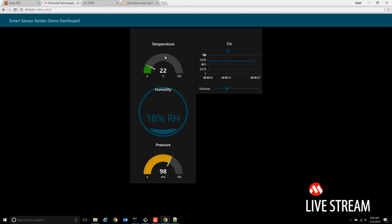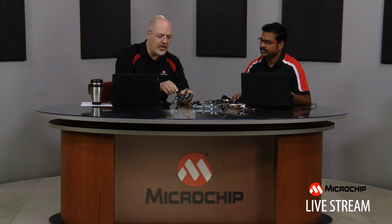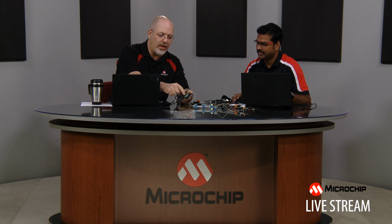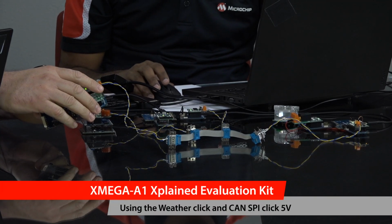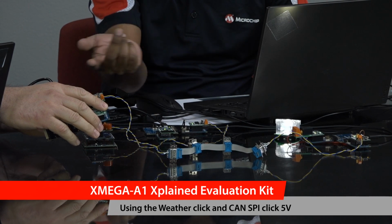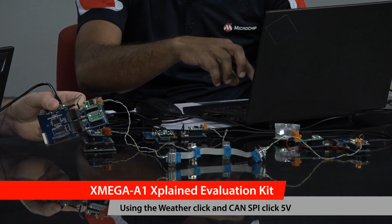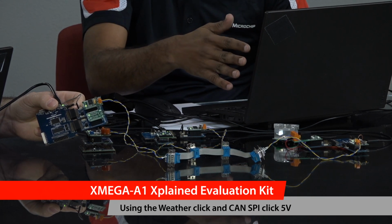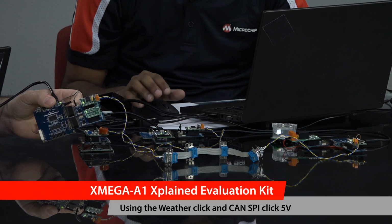If we go back to the camera, I'll just show. So this first node here has the CAN bus node, but it has a weather click on there. And this weather click has a humidity sensor. You would touch this humidity sensor. I'm going to go ahead and press that, and you'll see the light over here come on. What it really does is send the data over CAN, and this node receives it and processes it, and if it goes above the threshold, it turns on this light. Cool. So a kind of control system as well.